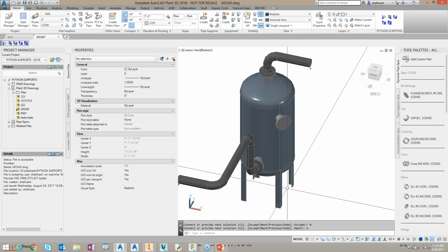So there's not a real-time change that can take place there. It's not a linked model in the Inventor model. Obviously it is an IAM file or an IPT, depending on how you model it, and then it really has to be an ADSK to bring it into Plant using this tool here. Now, I've noticed in 2018 that we can import IAMs and IPTs directly, and it does a conversion, but you're not going to get that real-time link back to the IAM file.